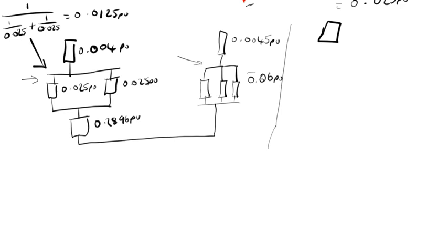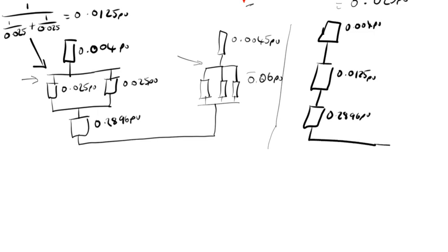and don't forget this is your faulty network here, so this is where your fault is. So then you would have your three transformer values using this same method here in parallel, but with the 0.06 figures, and that would come to 0.02 pu.